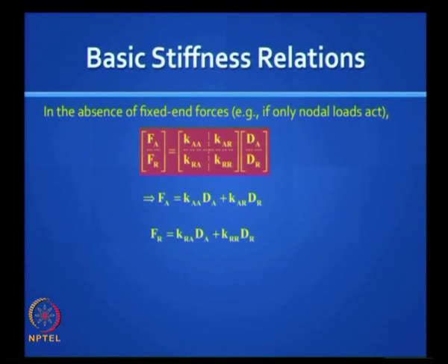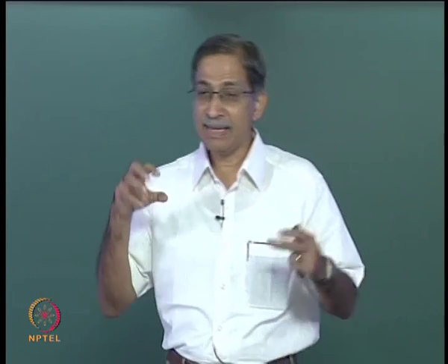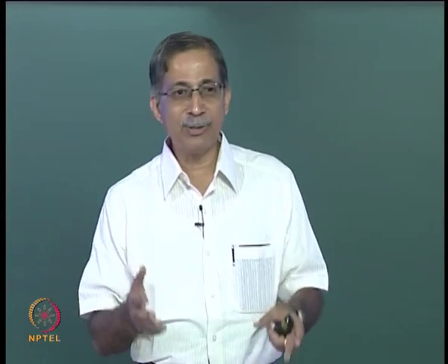So you can expand this into 2 equations, because the K matrix can be subdivided and they look like this. Does it make sense? So you need to solve the first equation, find out the unknown displacements dA, plug it into the second equation, you get the support reactions here from the global picture. Then the unknown displacements dA you should use, using equations similar to your slope deflection equations, and get the member level forces. Does it make sense? This is the big picture.